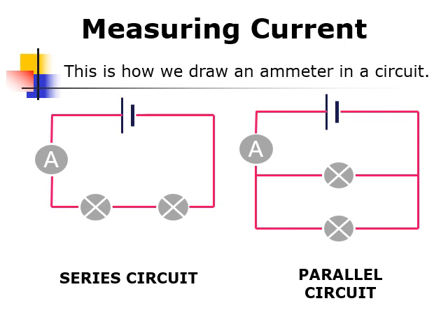For the parallel circuit here on the right, you place the ammeter after the two routes have reconnected, so you get all the current. Because we know now there's two routes the current can flow through, so the current's actually going to be split between these two light bulbs. So you place the ammeter in series with both of them up here after the routes converge.